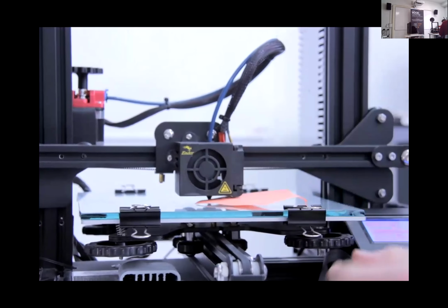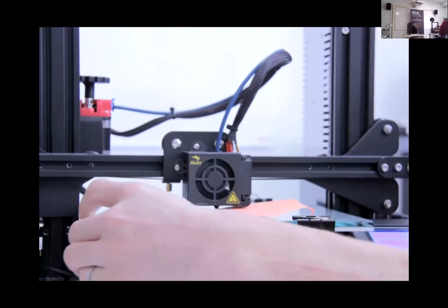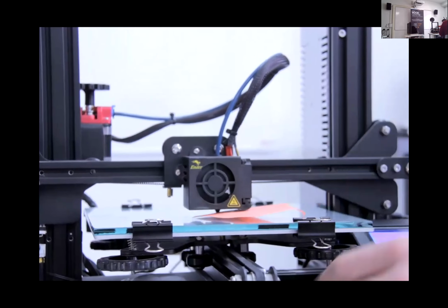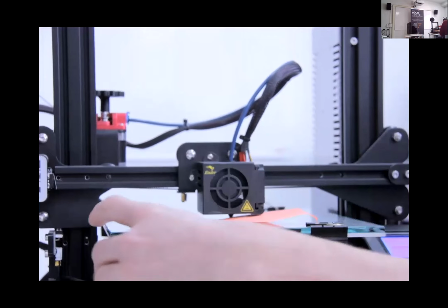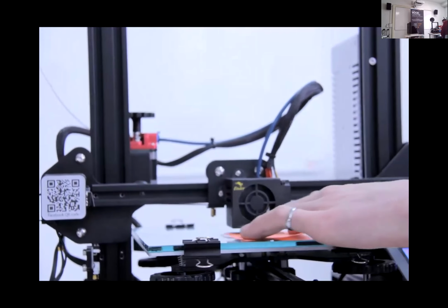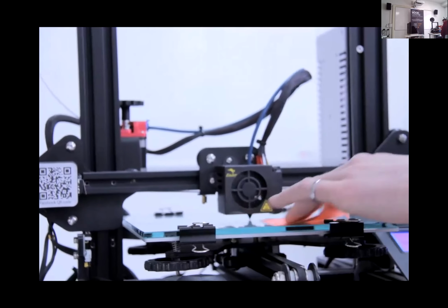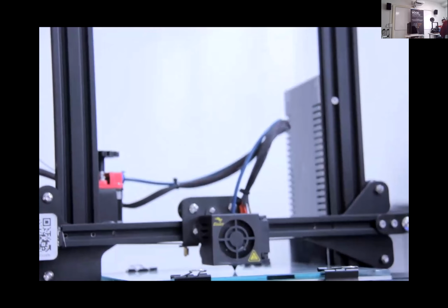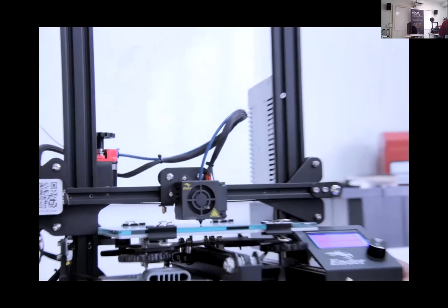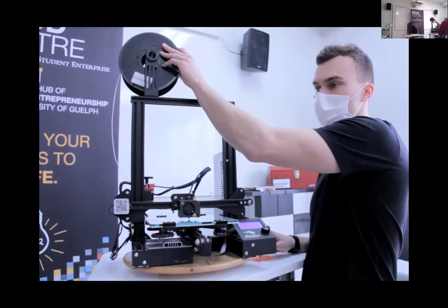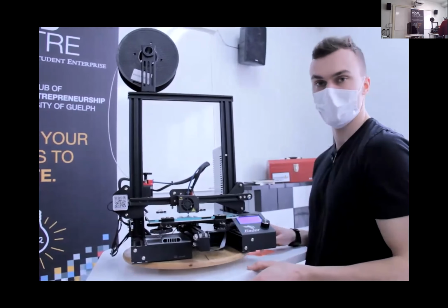Here it feels a bit high, so I would just lower these front 2 a little bit. Maybe a bit high still, so bring them down just a bit more. And that's better. So I'm happy that my print bed is level now. And once my print bed is level, I can start thinking about preheating my printer, putting the filament on that I want, and starting my print.